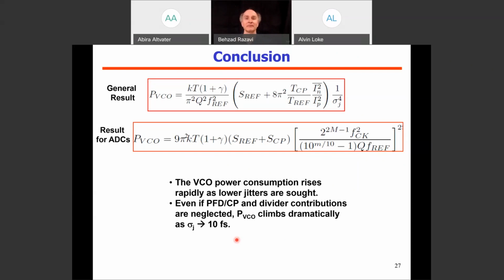So one is, do you see any difference between whether you have a Nyquist rate versus oversampled, for instance, like delta sigma ADCs, in terms of jitter tolerance? Good question. Yes. I don't think there's much difference. In the case of oversampling, we are taking a bunch of samples and in a sense averaging them. So we have some jitter averaging in that respect, but that's really equivalent to having designed a phase lock loop with a proportionally lower clock frequency, in other words, the effective sampling rate. I haven't analyzed that situation carefully, but my intuition is that there's not much difference between the two.